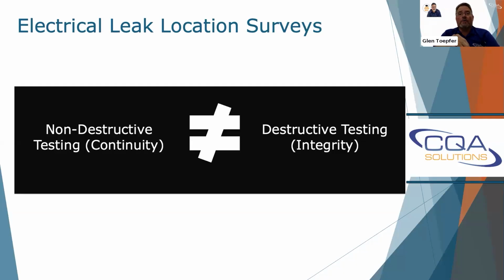Take a knife and gouge it 50% of the way through, 30 mils. That 30 mils isn't going to reach the conductive lining of the geomembrane, or I mean the conductive subgrade. So it's not a hole, so you're not going to get an arc. It's not going to detect. Take a tensile test of that. I can guarantee you, you're not going to meet your properties on the material. The two do not correlate.